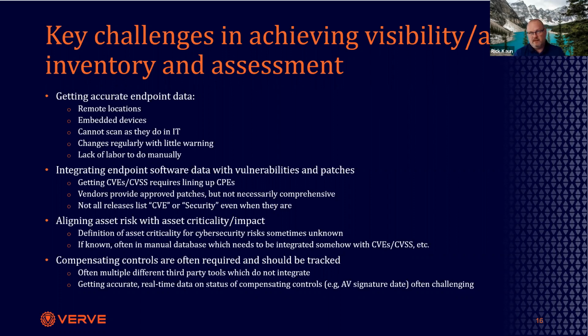We can't scan in OT. Vulnerability-based tools like Tenable, Qualys, et cetera, they're really good at understanding application vulnerabilities. They're not necessarily OS-based vulnerabilities, and they're certainly not built for embedded devices like relays, PLCs, and controllers, or even networking gear. In fact, many of my clients only scan IT-looking systems like Windows boxes and domain controllers in OT with scan-based tools under very controlled circumstances. So very periodic, maybe on a lower scan, maybe on the backup, the redundant pair, or maybe only during outage. So there's significant gaps in your visibility there. And those are built for discovering vulnerabilities, not inventory, really.